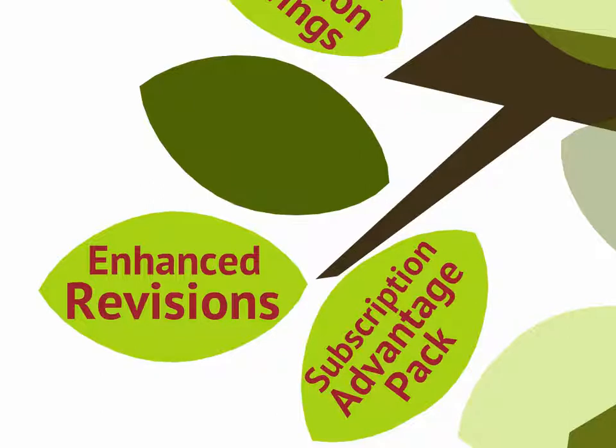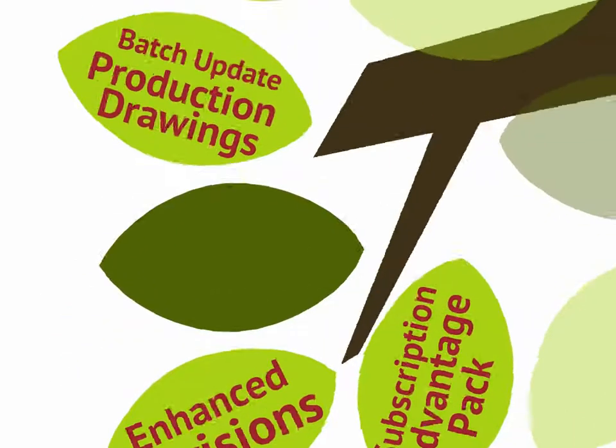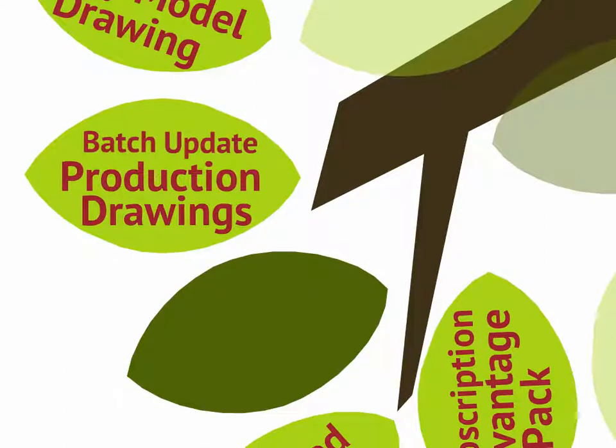But now we have a capability to do that, to track and find out what exactly occurred in our ShipConstructor project at any given time based on user dates, any other criteria you might want to see. Batch update of production drawings means if I've got a set of production drawings where I've made changes in the model and it might affect half a dozen different production drawings for output, I can now say, batch update all of those production drawings to show me the latest changes that might have occurred in my model without having to open each drawing, right? And then regenerate it, do the update, see what was changed, approve everything, say okay, and save it again. We can do it all in one go, right? Much faster approach to that.